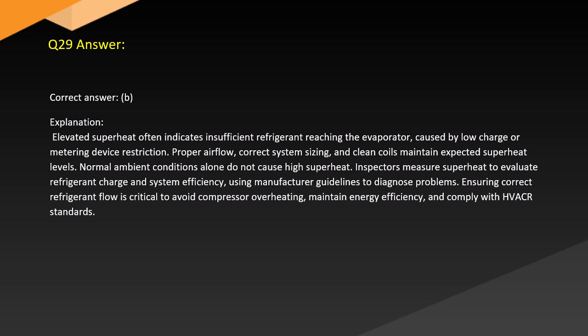Inspectors measure superheat to evaluate refrigerant charge and system efficiency using manufacturer guidelines to diagnose problems. Ensuring correct refrigerant flow is critical to avoid compressor overheating, maintain energy efficiency, and comply with HVACR standards.